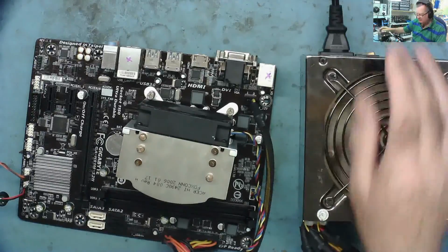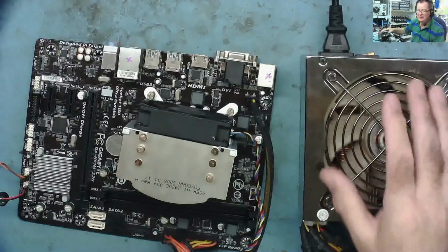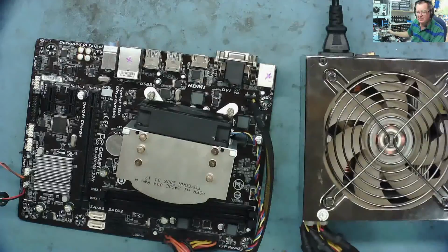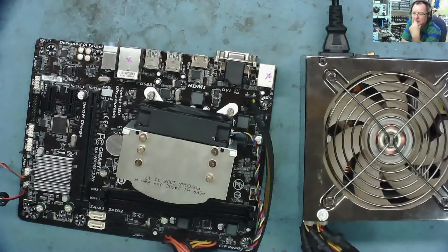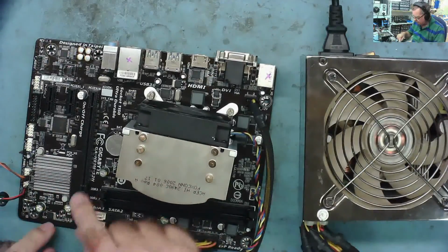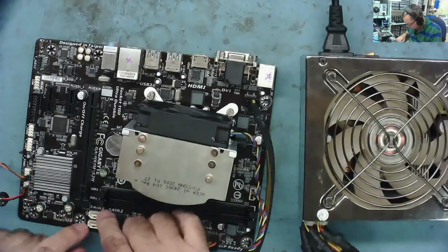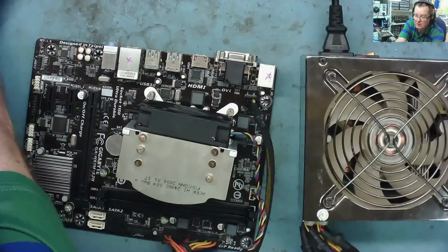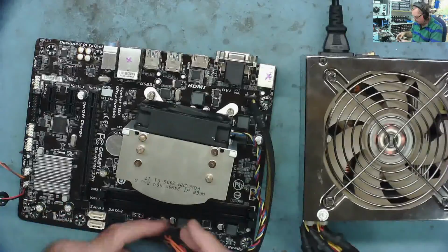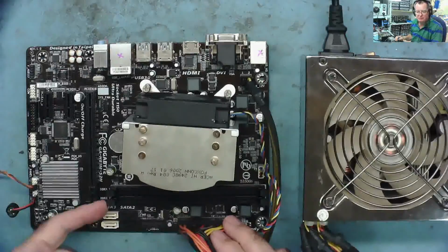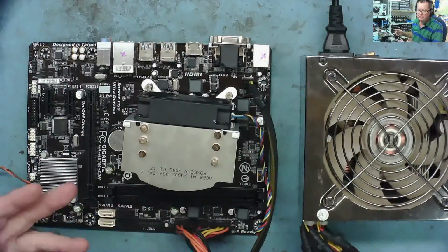And this makes me think that this is tripping out. Something's causing this to trip off and stay off when we do it that way. That's interesting. I'll go across all the board and measure all the coils and all these voltage regulators on this one, and compare them in resistance mode with the other board and see if I can see a short. Maybe not on the 3.3, the 5 or the 12, because they're okay, but a short on a lower voltage rail generated from one of these might cause it to trip out. That makes some sense.